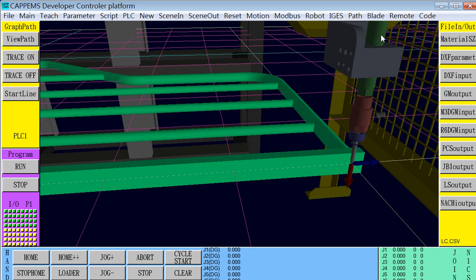We insert the tool and turn the tool with an angle between the square bar and the round bar, and insert in position for one spot welding, and then along the round circle weld up to the top, and retract the tool and turn the tool back to the B and C equal to 0 positions,